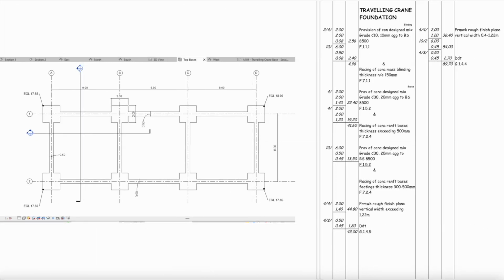We are now close to finishing with concreting, Class F. In CESMM4, concreting is in 2 parts. Provision of concrete, the total amount of a particular grade and aggregate size, and then a second part where it identifies where the concrete is to be placed. It's a recognition that concreting has two cost centres, one for provision, this could be ready mix or more likely the costs of setting up batching plants, quite common for civil engineering projects, and then quite separately the cost of placing concrete in different areas which may well have differing costs. In the BQ, the provision for each type are grouped as one and the placing grouped per structure.